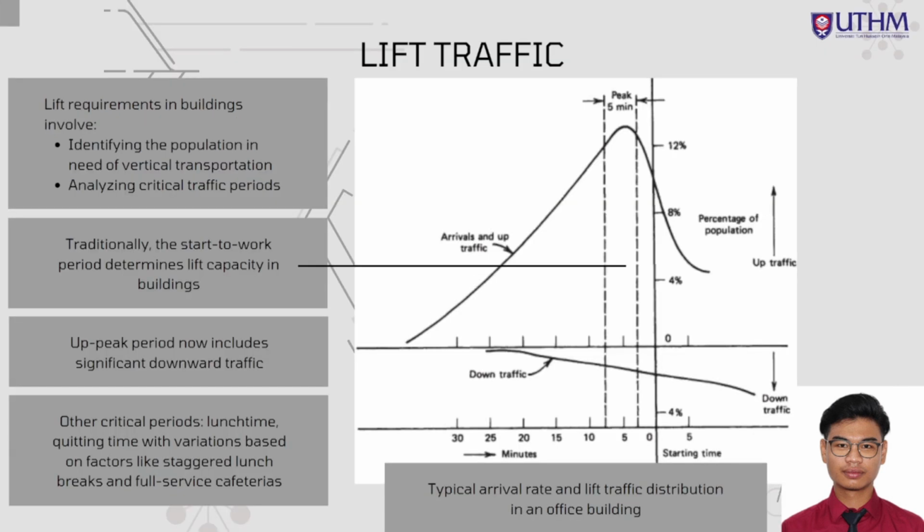Now, for the design considerations and factors, there is the lift traffic. In a simpler way, lift traffic studies are typically performed to determine the anticipated lift interval, the average waiting time, and handling capacity that propose a lift scheme.